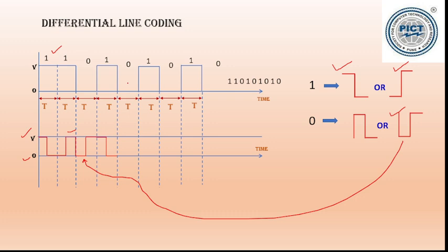Now 0 is there. So the signal level is at 0, which means we will be using this to represent the 0 here. Okay. So this is what the positive pulse is used to represent the 0. Now again next 1. We will use the reverse Z here. Now you can see that at the receiving end, the receiver will decode the signal as this is having this pulse, so this will be 0. This is having reverse Z, this will be 1. So this type of detecting capability improves over there for every transition.